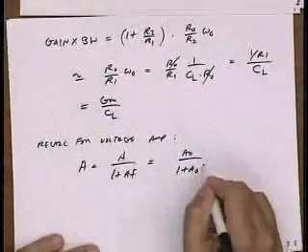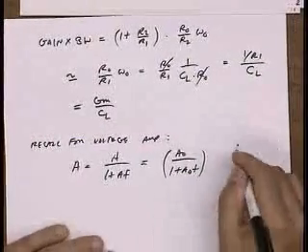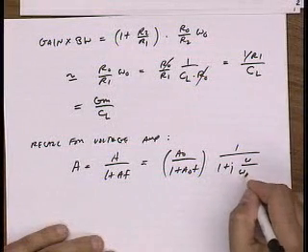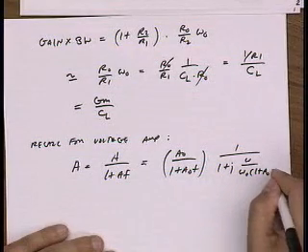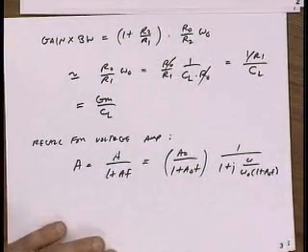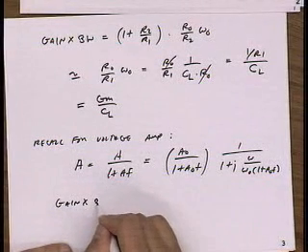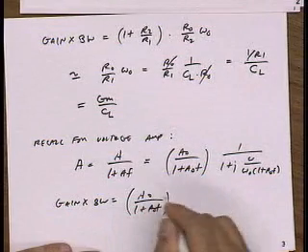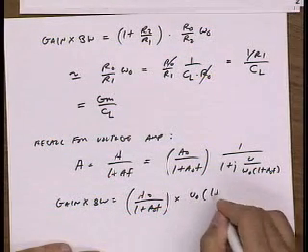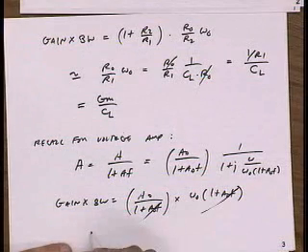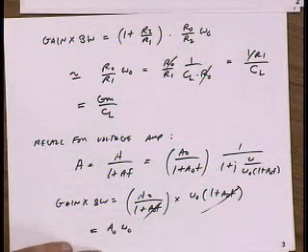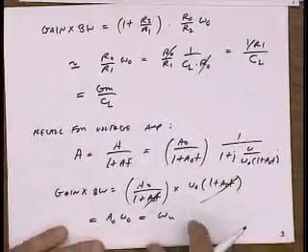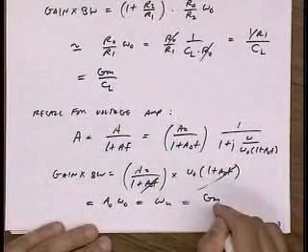So this is the closed loop gain, and then the bandwidth is the bandwidth of the open loop amplifier times 1 plus A naught F. So here, the gain times the bandwidth is A naught over 1 plus A naught F times omega naught times 1 plus A naught F. This term cancels out. The gain bandwidth is A naught times omega naught, which is the unity gain frequency of the amplifier, which is GM over CL.